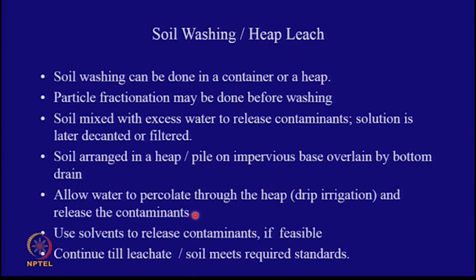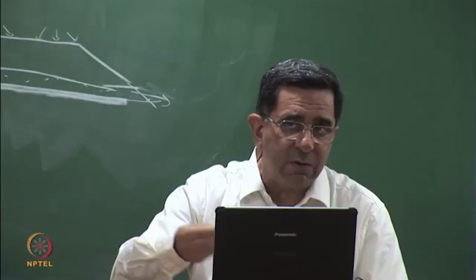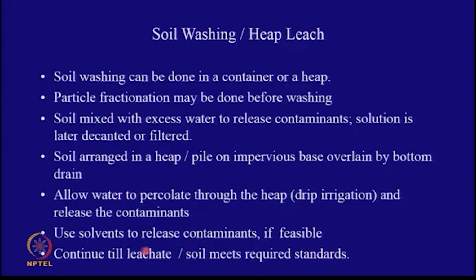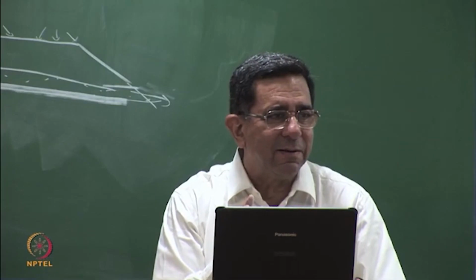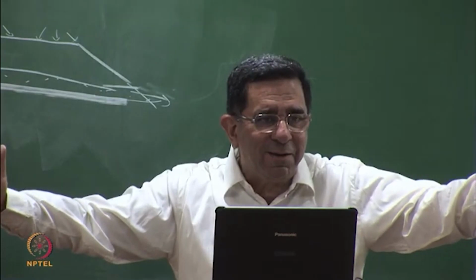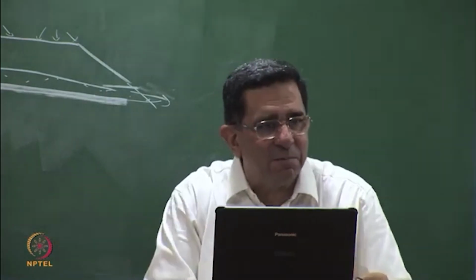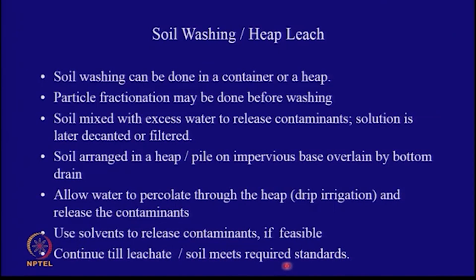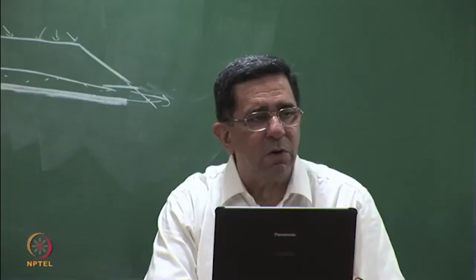Sometimes you may add a little chemical to the water, which is a solvent which will help faster release of the contaminants. That will depend on the chemistry of the problem. So, you can use solvents to release the contaminants also. This is actually like a mining technique. In the mine, you are trying to get the ore to come out of 99% of the rock. Here you are trying to get the contaminant to come out of a matrix which is full of soil only. So, you continue till the leachate of the soil meets the required standards. So, that is the concept of soil washing. Any question which bothers you about soil washing?